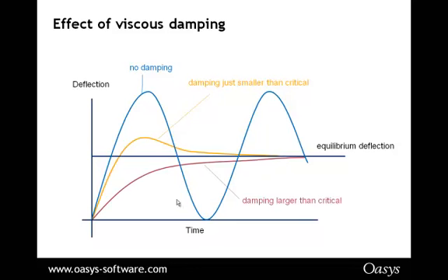And likewise, if the damping is too large, it won't overshoot, it will just take longer to reach convergence. And so knowing what the damping should be is quite tricky. So GSA has automatic damping calculations in there, which it will adjust as you go along. Sometimes these routines don't work, so you can go in and take manual control and actually adjust the damping yourself as part of the analysis.